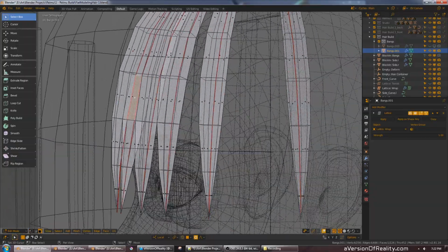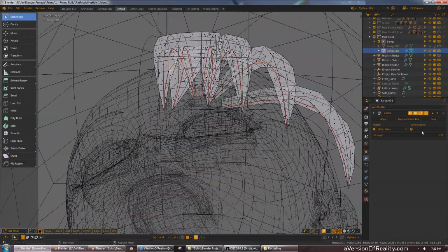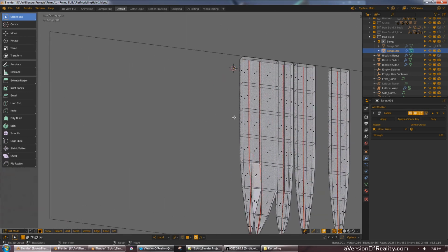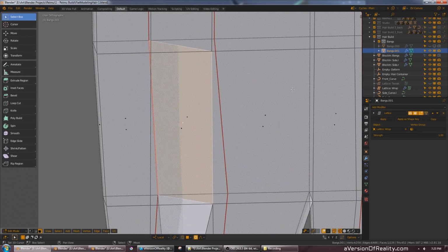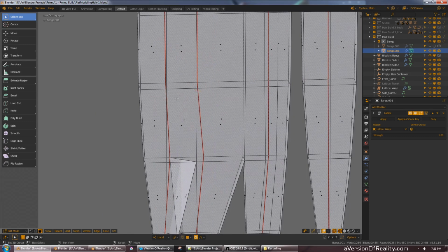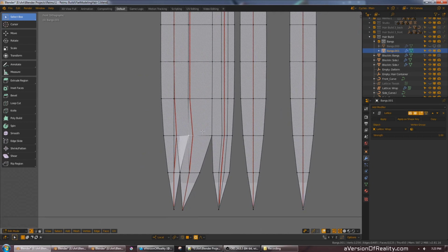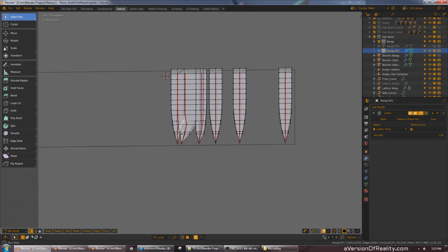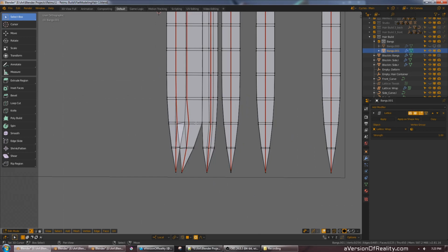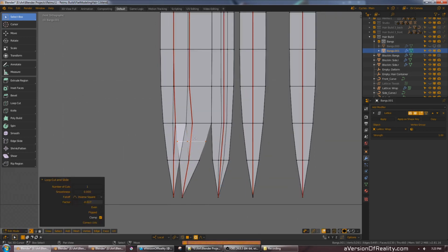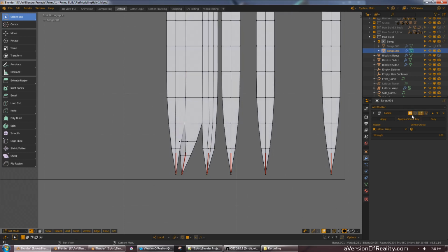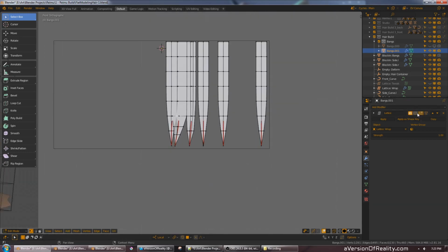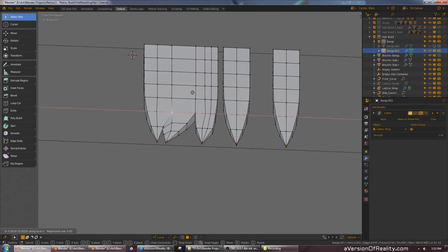Again, remove that internal face. Hard to see here. Flat. That point. If we want, we can add more edge loops in either direction, down with edge slide or regular move. And of course, if we want to see a full shaded view, we have to disable the modifier entirely in edit mode.